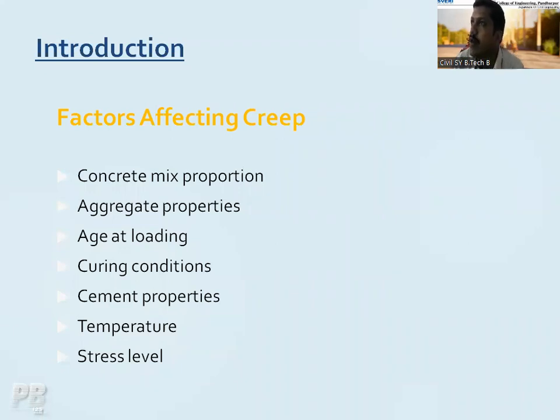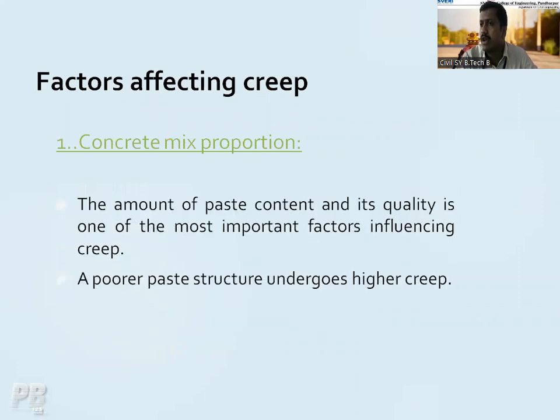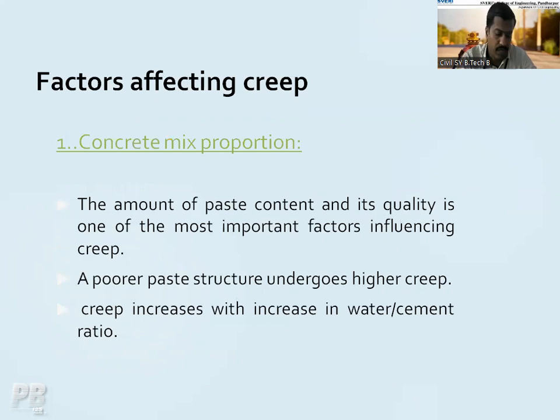Then cement properties: all the physical properties of the cement, like specific gravity, fineness, consistency, and setting time, all these affect creep. Temperature, another factor, the weather conditions, and the stress level, that is, what type of actual load acts upon the concrete body. These factors we have discussed, so I will not take much time on this.